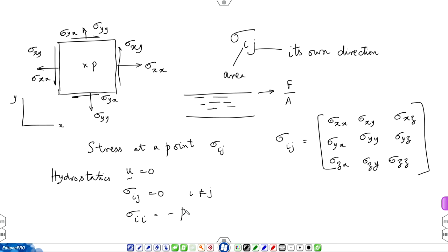Okay, so this is the background. Now, what did we do in hydrostatics? In hydrostatics, we set up a governing equation that gave us the pressure distribution. Once we had the pressure distribution, we integrated pressure to find forces and moments and points of action. So, the basic calculation was for finding the pressure distribution. So, you can call that equation that we had, minus dP dz equal to rho g, the governing equation for hydrostatics.